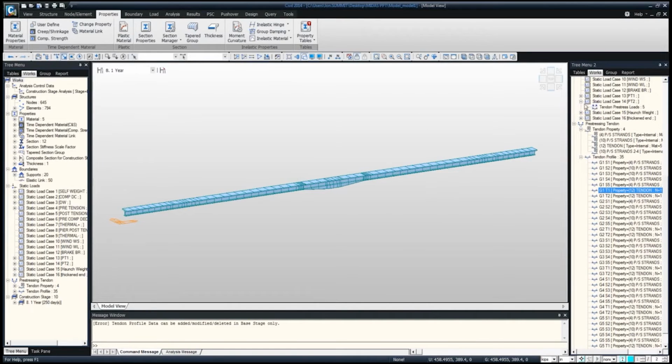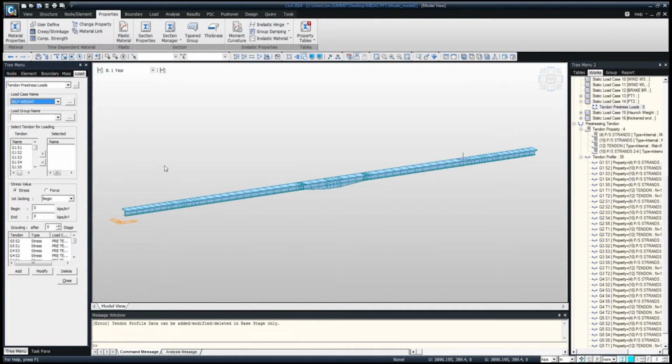As I mentioned, we define the tendon, then we define the pattern, and then we define the load. So I'll open the loads up here. We'll take a look at that on one of the continuities here. So here we're in girder 1, and it's the second continuity tendon. In this case, I'm stressing from both ends to 0.75. This also gives me the option to stress from the beginning or just the far end. In this case, I will be doing from both.